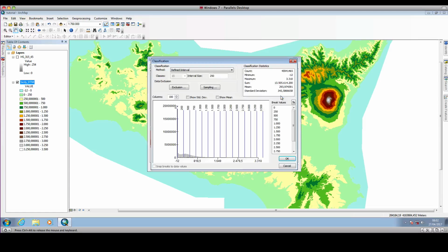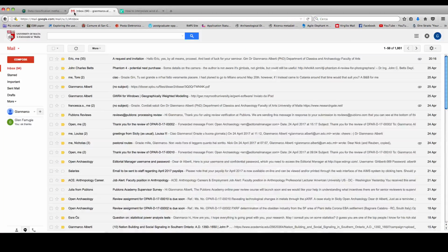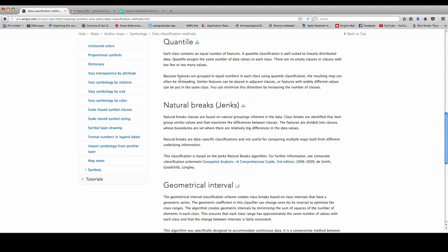We have different types of categorization. We could use the natural breaks. That is a method that was proposed by this guy, Jenks, and you can get some information from the online help of ArcMap about the natural breaks Jenks.